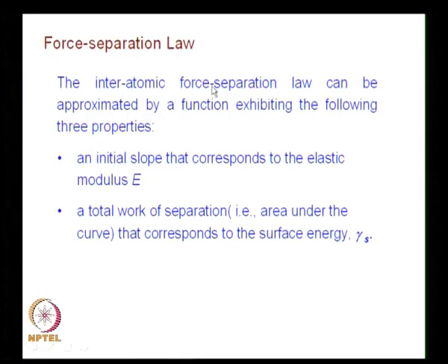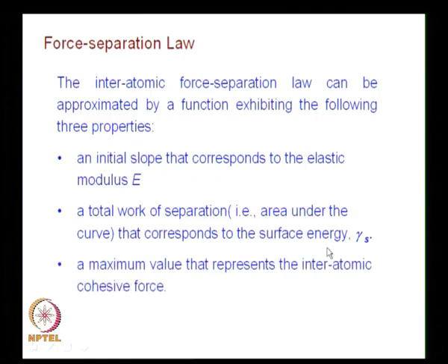So, you need to have the force separation law to have an initial slope that corresponds to the elastic modulus E, total work of separation, that is the area under the curve, corresponds to the surface energy gamma s, and finally you should have the amplitude, a maximum value that represents the interatomic cohesive force.